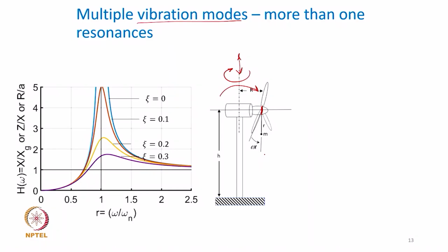Okay. And there is no reason for us to say that the torsional vibration natural frequency would be same as the bending vibration natural frequency, would be same as the longitudinal vibration natural frequency. They will be different, of course, is it not? So, maybe the torsional natural frequency here could be maybe 20 hertz, bending natural frequency may be 55 hertz, the longitudinal natural frequency may be 270 hertz, and so on. So, I have 3 different natural frequencies to cater to.